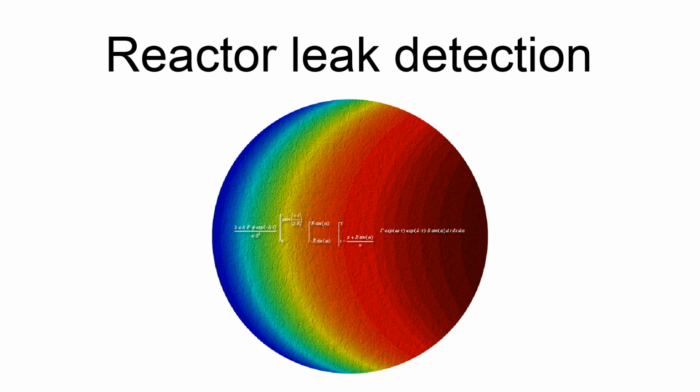Leakage from the so-called reactor coolant pressure boundary is required to be monitored in USA nuclear power plants. Monitoring the airborne particulate radioactivity in the reactor containment structure is an acceptable method to meet this requirement, and so CPAMs are used. When primary coolant escapes into the containment structure, certain noble gas nuclides become airborne and subsequently decay into particulate nuclides. One of the most common of these pairs is 88Kr and 88Rb. The latter is detected by the CPAM. Relating the observed CPAM response to the 88Rb back to a leakage rate from the primary system is far from trivial.